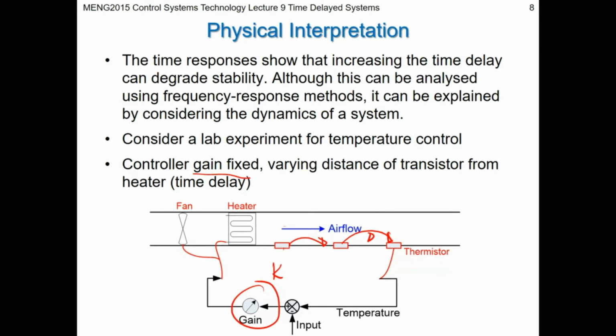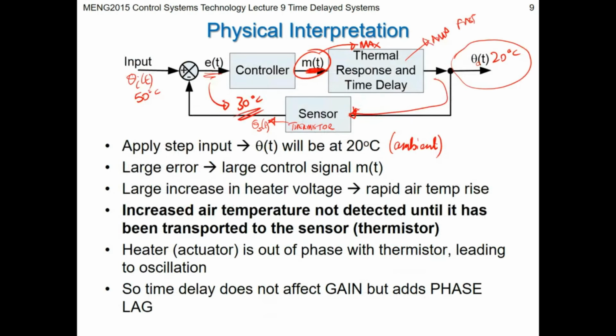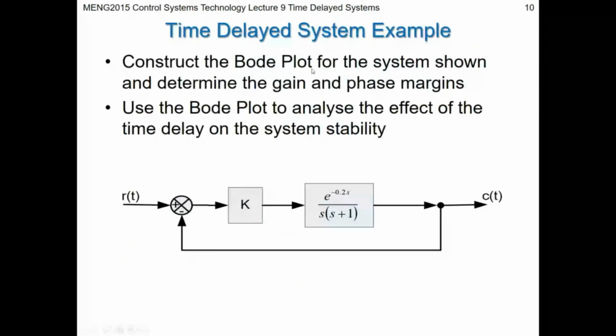That lag time is going to create an out of phase condition where the output is ramped up much before the sensor detects that ramp up, and so the sensor starts to ramp up out of phase. And of course, that sensor ramping up out of phase means that you have an out of phase error as well. The error here will also be out of phase, right? And so you kind of get this unstable condition.